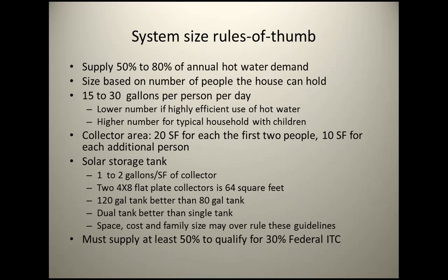Make sense? So to answer your question, the trade is between having a large volume, which takes longer to heat up, but you can sustain many more cloudy days because you have so much water that's hot. With a smaller tank, it gets hot really quick, but then you use it up really quick and it's gone. So you have to have sun each day to keep heating up the tank.